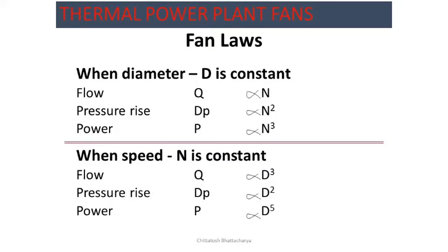That means differential pressure developed across the fan, and power consumption to run the fan or horsepower, is proportional to RPM cube.